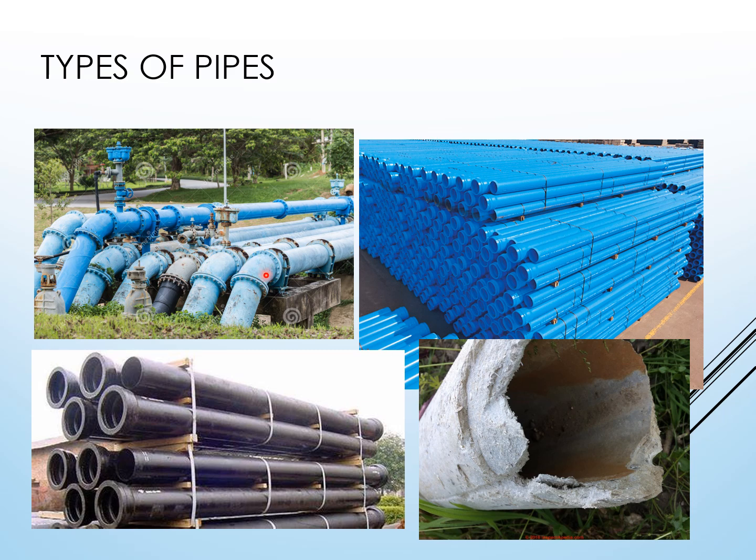This is probably a ductile angle, looks like maybe a 22 and a half. And then steel pipes above ground are usually coated in some kind of an epoxy. Other pipes, you've got PVC here. That's going to be buried pipe. You don't want to have that sitting out getting damaged by UV.